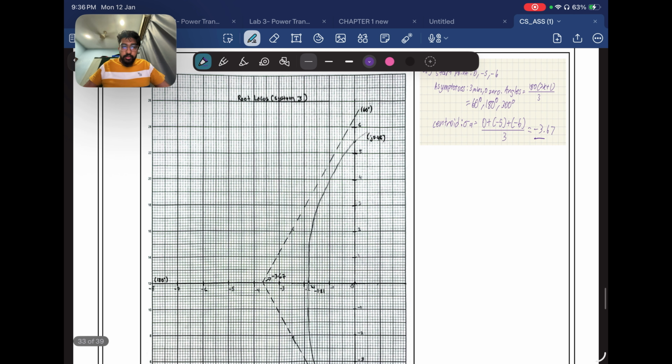the behavior and stability of 3 unity feedback control systems were analyzed using root locus, time domain response, and frequency domain methods. The open loop poles and zeros were identified to understand how the system dynamics change with varying gain K. Root locus plots were used to determine breakaway and break-in points, imaginary axis crossing, and suitable gain ranges for overdamped, critically damped, underdamped, and undamped response.